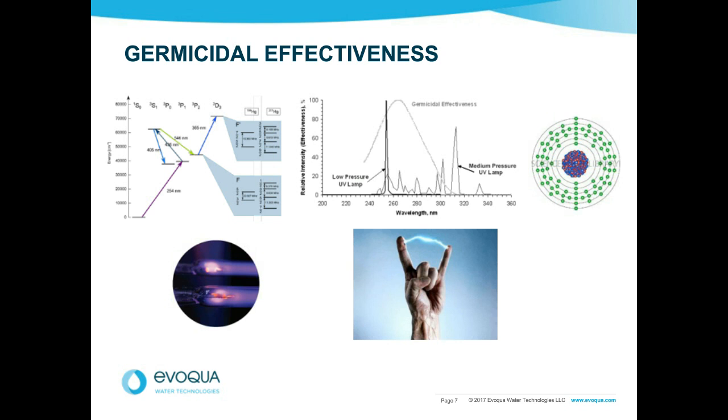Okay. Next question is: I've heard that UV systems validated in Europe require more energy and underperform because they are required to use ozone-free quartz. Is this true? It is. Yes, the Germans have a certain standard called the DVGW. The Austrians have an O-norm standard, and they are indeed required to put additives into the quartz. They have a very specific dose. They validate around a dose of 40 millijoules.